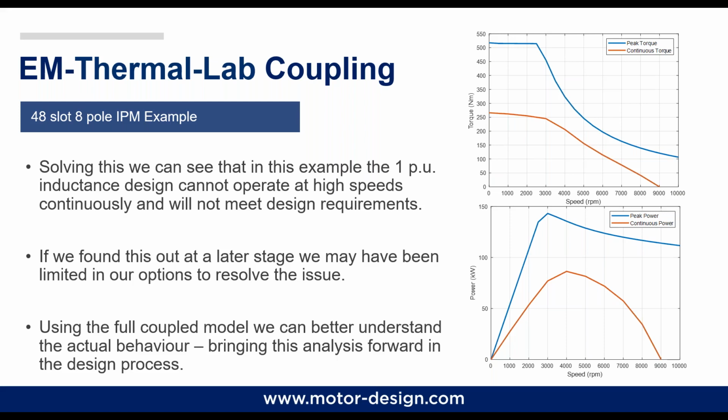It might be that this is limited, for example, by a constraint on the rotor temperature. So we need to figure out how to reduce the magnet losses, or how we need to change the cooling system of the machine. So it's important to understand from the beginning what we need to do for getting this machine able to work.